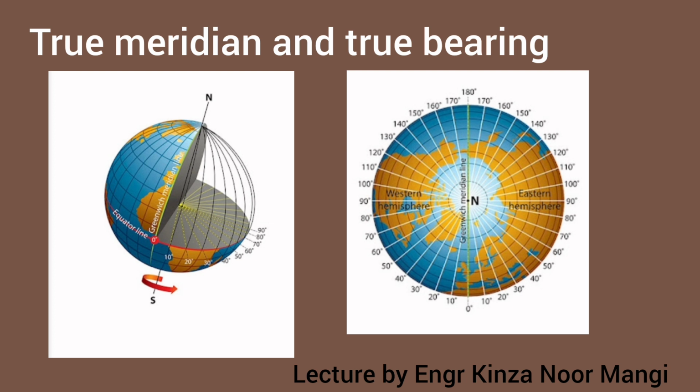Now, the angle made by the true meridian and a given line is called the bearing, or simply, bearing is the angle between the lines. If the angle is made between the true meridian and a given line, then it is known as the true bearing. And this must be kept in mind, that these bearings are horizontal angles, and these bearings are also known as azimuth.